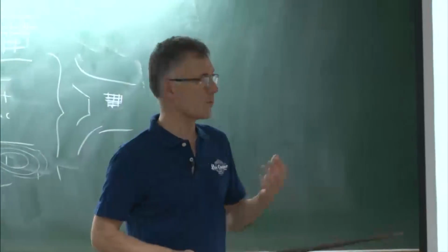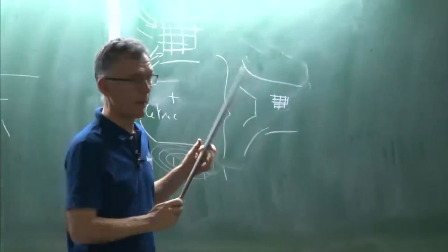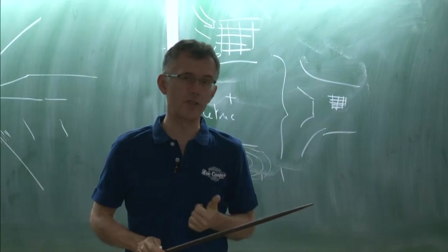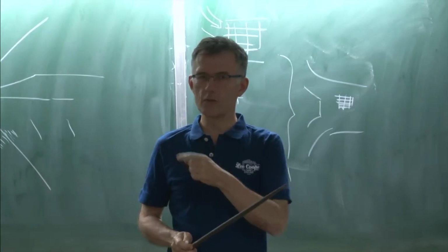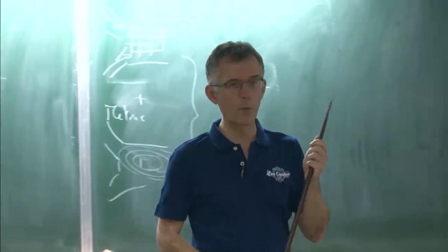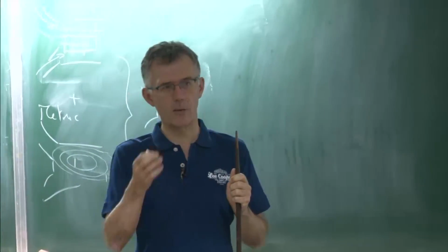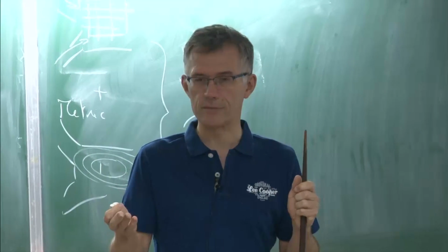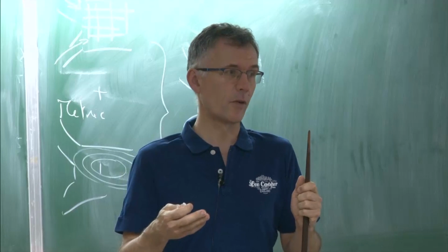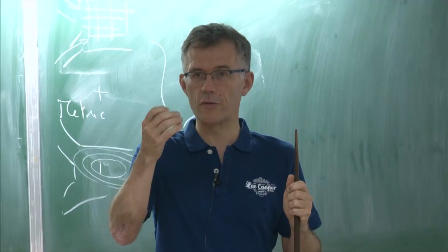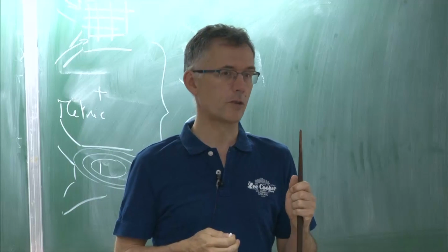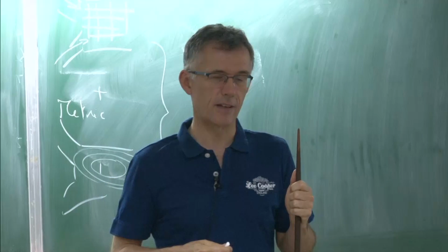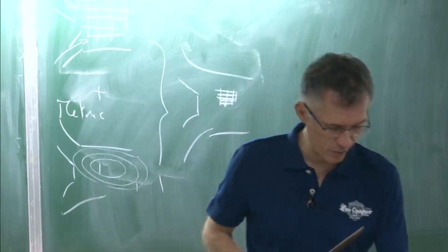So if you think about non-reacting flow here, for example, there are many things that could be a good metric. One of them could be the turbulent viscosity. Some of you actually have shown me some results, by using the Pope's criterion, where you try to quantify how much energy is resolved, how much energy is not resolved. So the Pope criterion could be a good metric. But it could be also the distance between the wall and the first point, the y plus. Or it could be the vorticity. It could be anything. So the problem is, which one do you want? And which one is good? Well, this is where you have many choices.